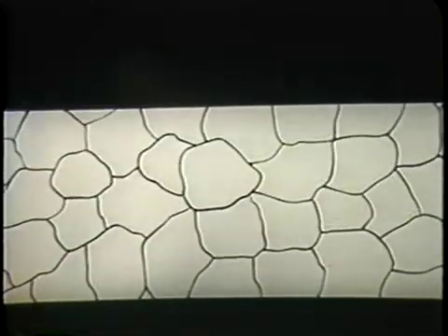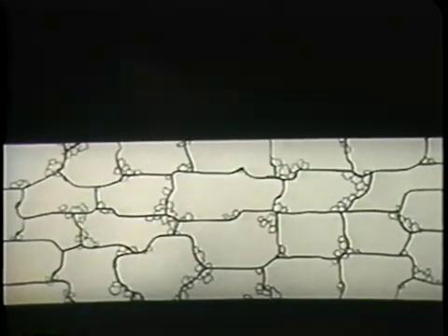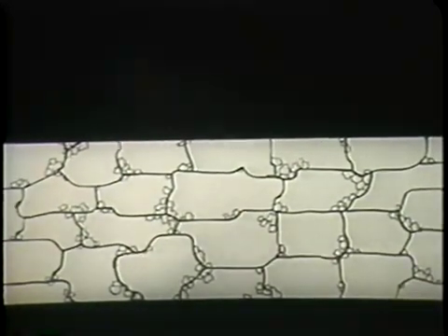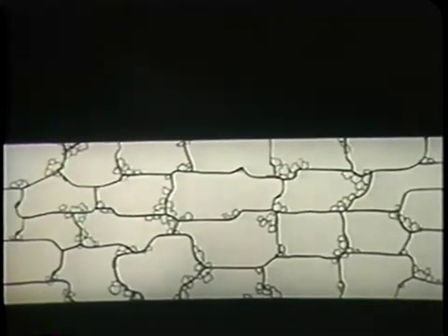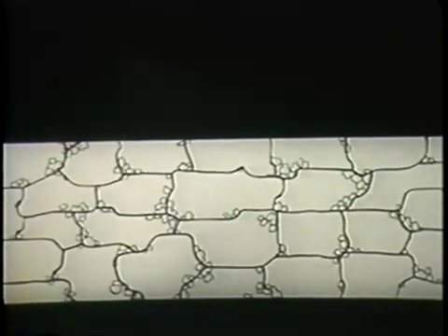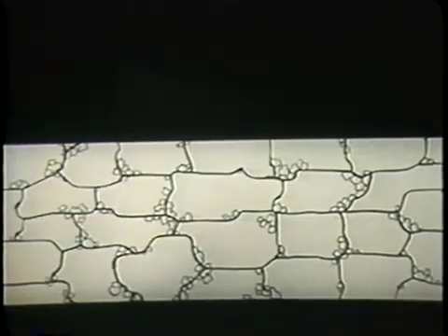Under the type of load applied in the bending and stretch forming processes, the grain structure of the aluminum alloy changes in a manner similar to that shown for the cold rolling and stretching processes. The grains rotate along the active slip planes and become elongated, and the metal is strain hardened. The cold working involved in the hammering, hydropress forming, drop hammering, and deep drawing operations results in grain rotation and elongation. But since the plastic deformation is generally more severe, fragmentation and crushing of the grains also occur.